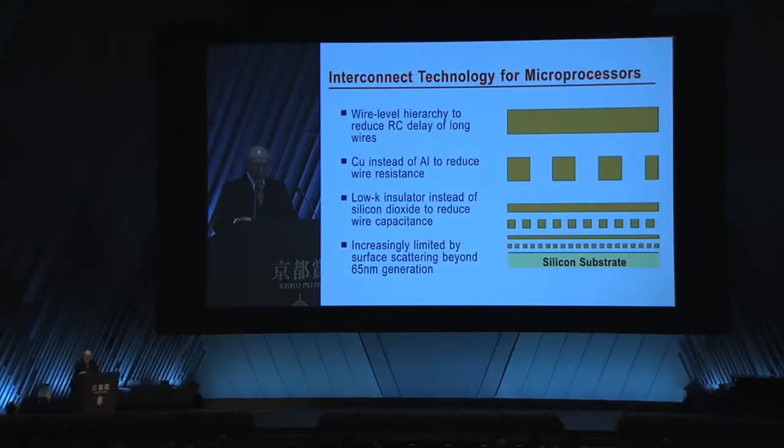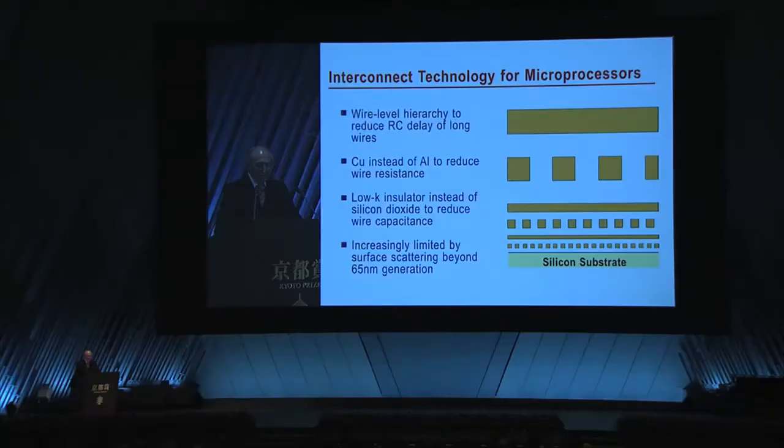Other thick wiring layers at the top can be used to bring in power for the chip and to distribute clock signals across the whole chip to synchronize the processor functions. A lot of analysis and modeling was done at Stanford University and elsewhere to show that such a system can work. It has been used in many generations of MOS technology, gradually adding more layers with even smaller scale wires at the bottom and even larger and thicker wires at the top. Also, a whole new set of materials were introduced, with copper wires for lower resistance and better insulator material for lower capacitance.